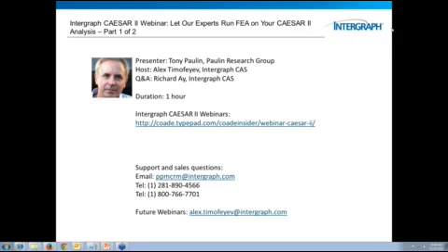Okay, let's see, this is from Dave. Several questions. We're expecting FEA tools to evaluate components. Can you state that the tool is mainly for modeling components more accurately instead? Yeah, FEA tools does have a component modeler in it, and the components that it models are bends with stanchions, bends with steel. It models pressure vessel heads with nozzles, pressure vessel heads with offset nozzles, vessels with hillside nozzles. So those components it evaluates.